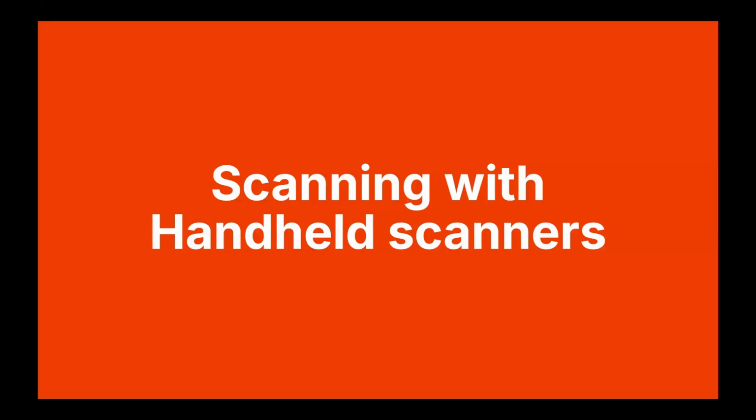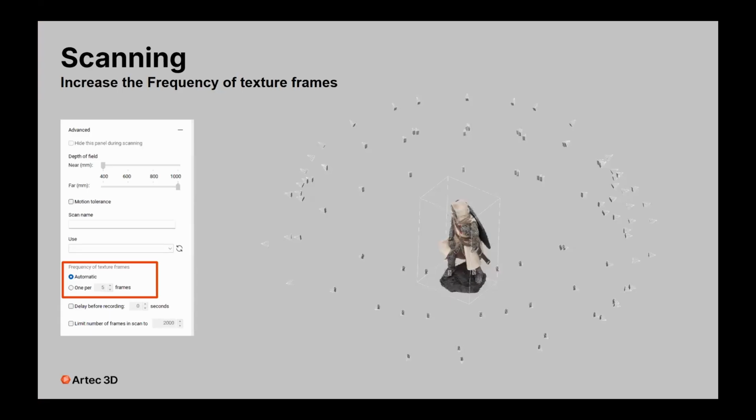Okay, so first of all, let's talk about scanning with our handheld scanners. When I'm saying handheld scanners, I'm referring to Artec Leo, Eva, Space Spider, and Spider II. The first advice, which will give you the most noticeable impact on texturing, is increasing the frequency of texture frames. You may find this option on the scan tab, if you scroll down and extend the advanced settings.